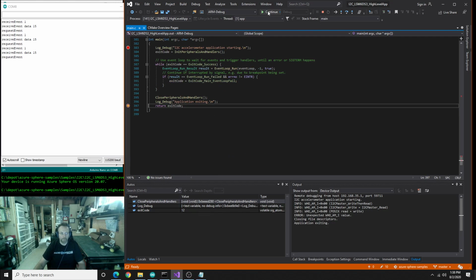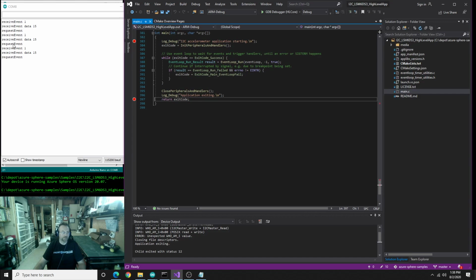Perfect. All right. Cool. So that's exciting. We now receive each time it's sending us a byte. We see that. And we saw that if we don't read as many bytes as it told us, it will get stuck and we won't be able to get any more receive events until we've done the reading that we need to do.